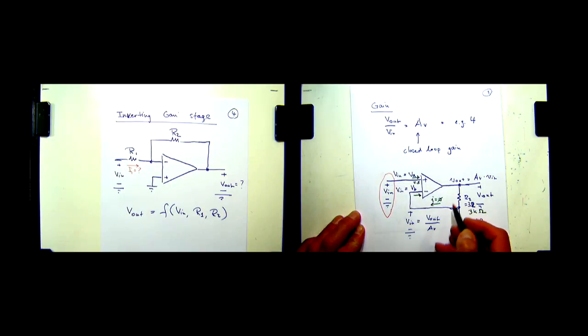So first, what do we have to do first? What's the first step if we analyze a circuit with an op-amp? Well, we have to determine if our conditions are met. The first condition is that the op-amp is ideal. Well, that's always the case in EECS 16A. The second thing is we have to verify something about the feedback. What is it? Negative feedback, right? Here we have negative feedback because if we go around the loop here, we go through the minus terminal.